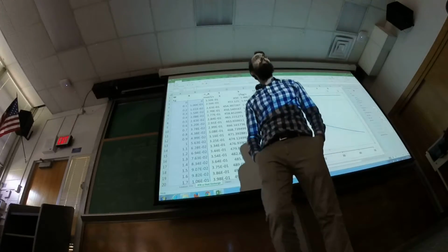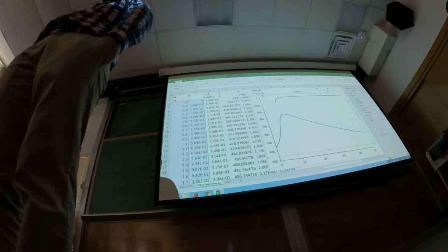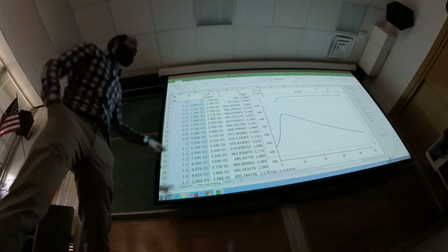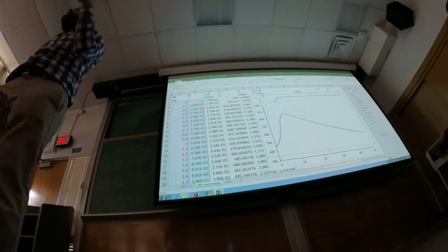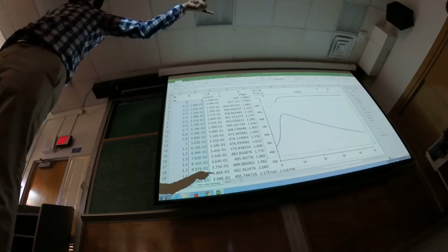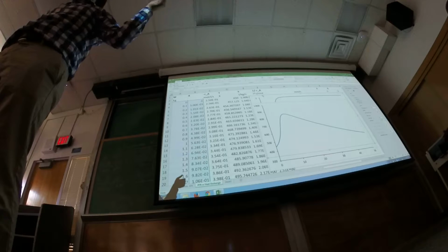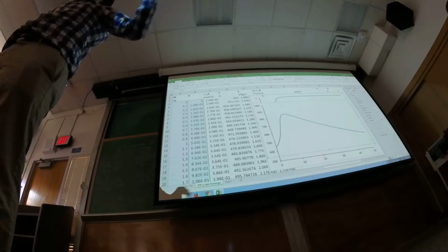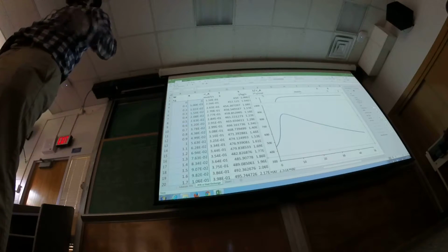Yeah? Will it eventually go down to reach 300? Yes. Once we hit 300, we can no longer cool. The driving force, the entire numerator, right? That's our driving force. The conversion is constant, so the rate is 0. And that was rate times delta H of reaction, so that term goes away. And then the first term has TA minus T. So if those temperatures are the same, the driving force for the entire process is 0.